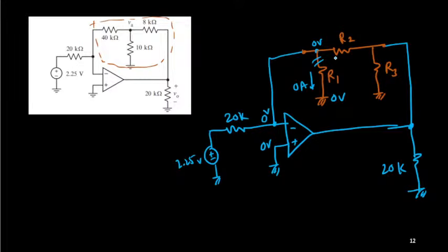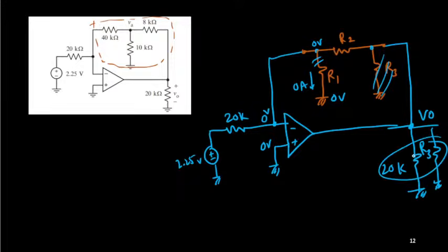Okay. Now this R3 is connected to output side. So instead of this one, I can connect it here. This is your R3. Same thing. And already I have said that if you have defined load, it does not matter. If op-amp is ideal, you will be getting the same output voltage. So output voltage does not depend on all those things. So what is left? Input side 20K, this is your R1 equal to 20K, and this is your RF. RF equals to simple R2.